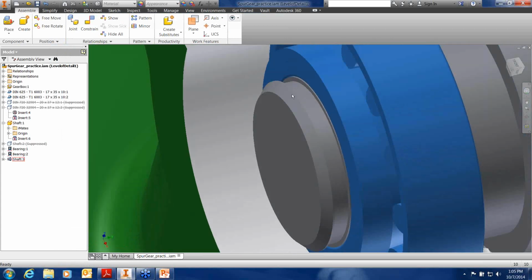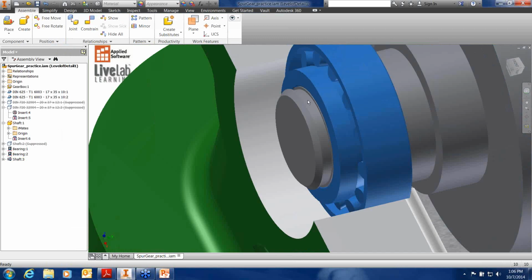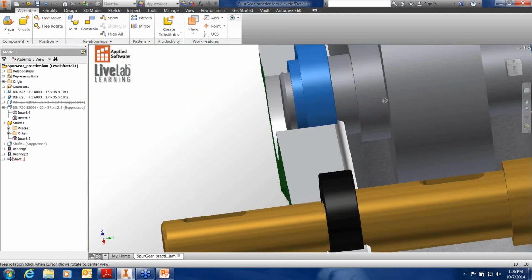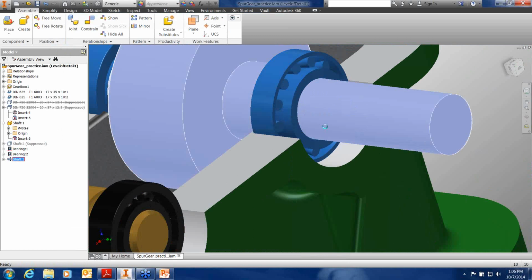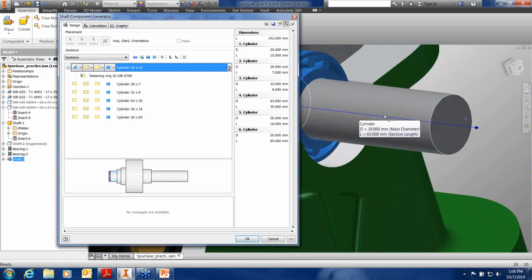And so now you can see it's gone ahead, based on the retaining clip that we're setting this up to be designed for. It's put in the depth it needs to come into as well as the width. Now we'll go over to the other side real quick. I'm going to select right here, right click, edit using the Design Accelerator.